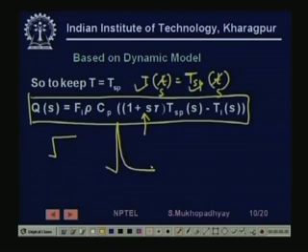input. So actually this controller is not very easily realizable, and you cannot give such command changes. Mathematically it's okay, you can always equate, but this equation tells you that if there is a set point change and you want the temperature to exactly follow the set point change, then you have to give an impulse input to the process, which is clearly not possible. There will be saturations of actuators and the response will not be realized, but for slower varying set point changes these things can be done.